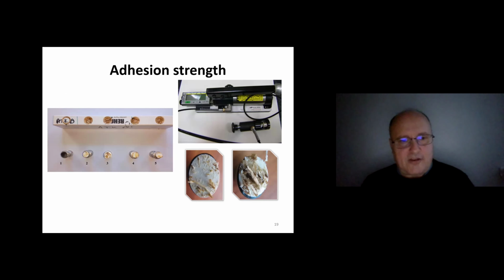What is the best method for analysis? We adopted the standard pull-off method. Some of you remember my presentations because this method, the pull-off method for adhesion strength estimation, is recommended for lacquer coatings, but we use smaller stamps for edges.